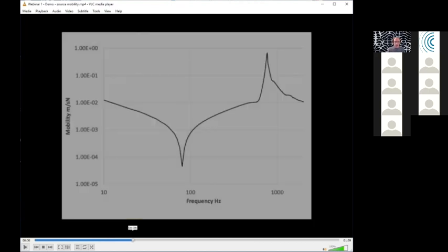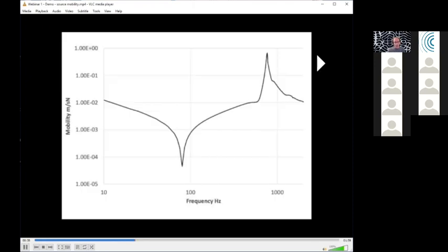Okay, so here we have the results, the measured mobility of that cylindrical mass with that strip acting as a cantilever, and we're measuring on the outer edge. Now, thinking back to what you saw with Gary's calibration before, when we just looked at the simple lump mass, we just had a straight line. So the first thing that strikes you is that, yes, this mobility curve is more complex. We don't just have a single gradient slope anymore, but there are features that we can relate to it.